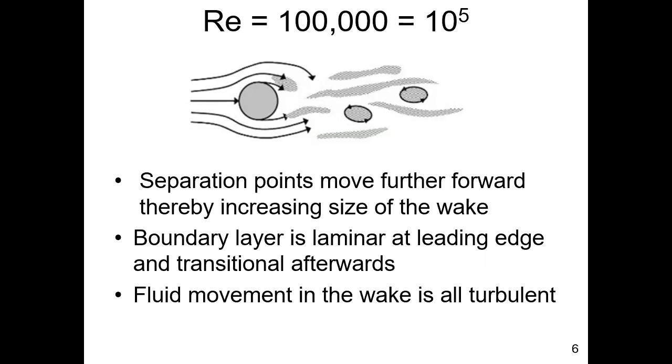So for example, as we hit the leading edge, the flow field is curving to match what's happening in the object. And as it goes to the trailing edge, again, now the flow field is expanding. And when we have that contraction and expansion, what we're doing is converting between v squared over 2g and p over gamma. We're making an energy conversion.